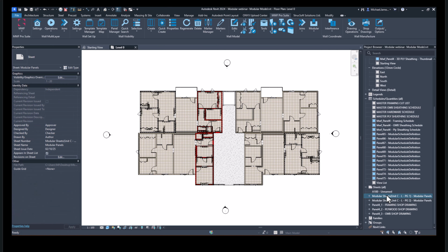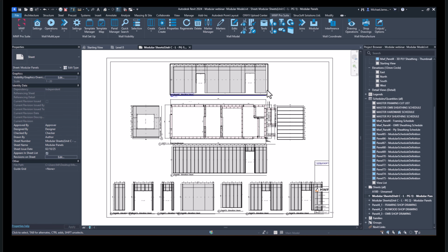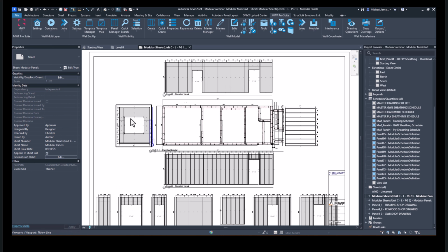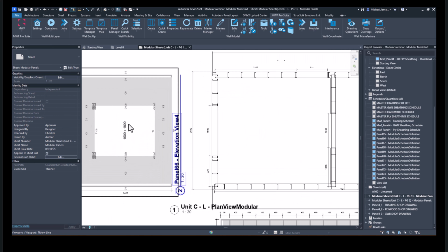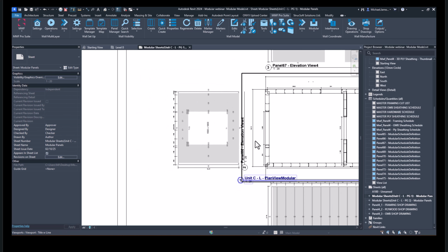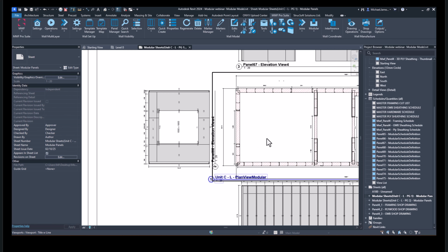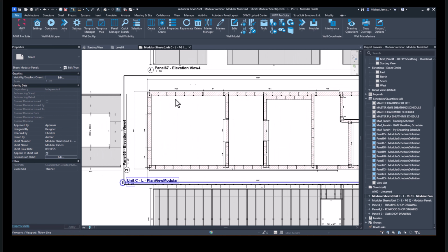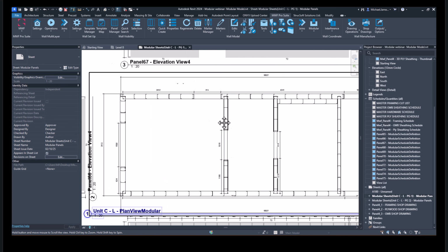So first, let's take a look at the physical panels. You'll notice it places our elevations in alignment with our plan view as we requested in the settings. We have dimensions which are placed as well to each structural member. You may need to play around with some of the visibility settings to ensure you get the kind of output you expect. You can see we've got our sheathing boards. We are labeling those members which make up the panel as well. So we have a number of cripple members, all of these different things which we can activate within our other sheet settings. In our plan view, this is also dimensioned based on the length of our panels.